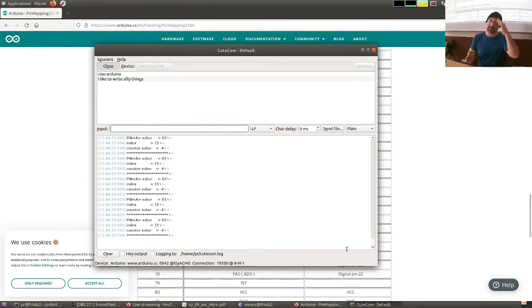So I hope that this exercise is clear, because we will build on it. My plan would be on next Thursday to control a motor in closed loop. Now we have the first part, because we can read the encoder. And the second part will be to issue a PWM, so a signal to the motor that moves it forward or backward with a little bit of black magic, and then we will be able to have a device that controls in real time a motor in closed loop, which means that we issue a velocity and the motor will follow that velocity through a controller.